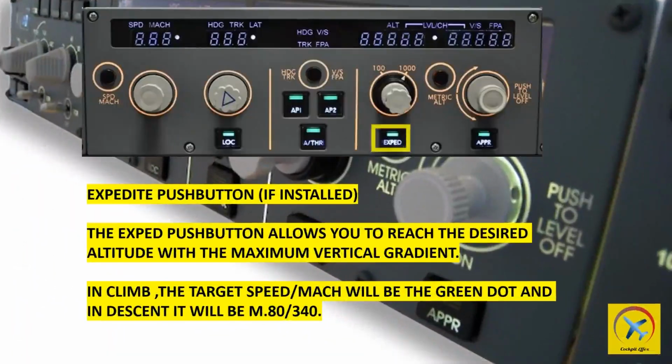The expedite button engages the expedite mode to reach the altitude set in the altitude window with maximum vertical gradient. It automatically engages managed speed. Airspeed is green dot during climb, and 0.80 Mach or 340 knots indicated airspeed during descent. To disengage expedite, select a new vertical mode or selected speed. Expedite climb is not recommended above flight level 25,000 feet because the Mach number corresponding to green dot is too low.